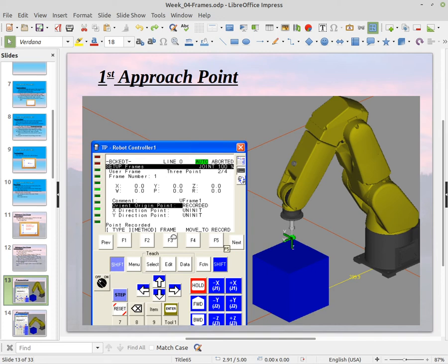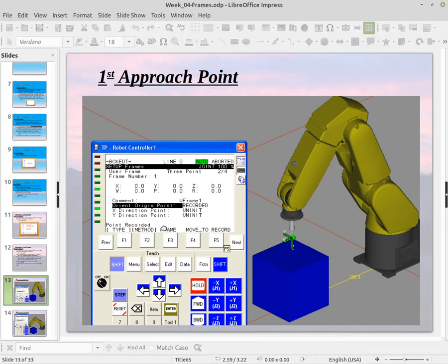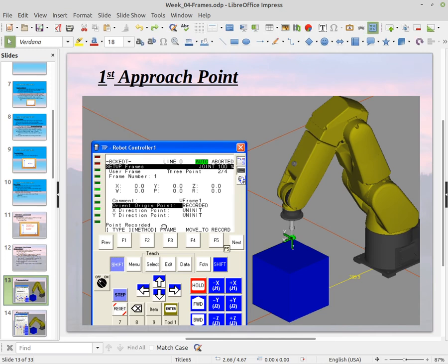And so when you press that, you would have your choice between tool frame, user frame, and jog frame. All right, and then it would list all the different frames that are available, and then you would select one of those frames, and you get into this frame. Now you notice up here it actually says user frame at the top, and that I'm currently in frame number 1. And you see the values are all zeros here. All the values are 0, 0, 0 for this user frame. And that's the default for all user frames when you first start out with the robot.